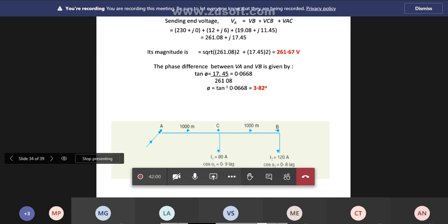They have given another problem, which I am not putting in the slide. Let us just listen. Consider the single phase radial distributor shown in the figure. Magnitude of load currents, power factor and distance are indicated in the figure. Resistance and reactance of each wire are 0.1 ohm per kilometer and 0.2 ohm per kilometer respectively. It is required to maintain voltage at point B as 230 at an angle 0 degrees. Find the voltage drop in the three sections and total voltage drop in the feeder. Power factor angles of individual loads.